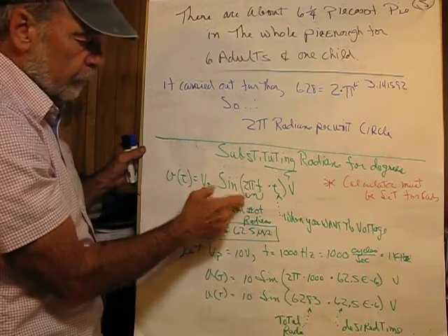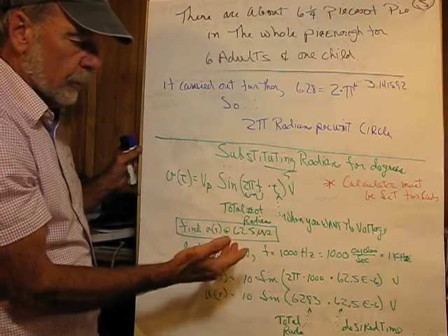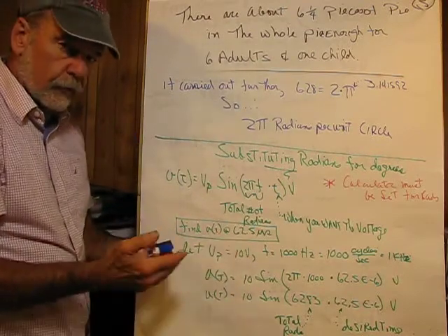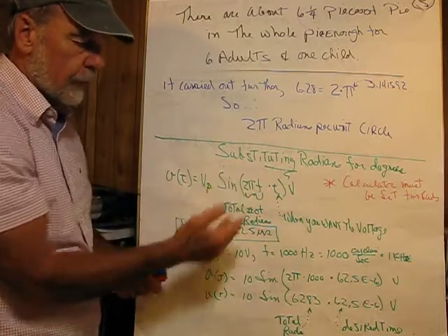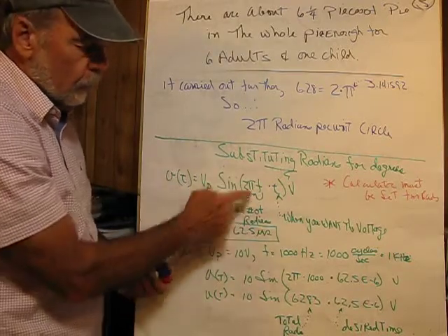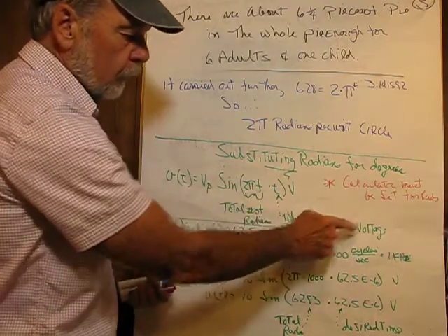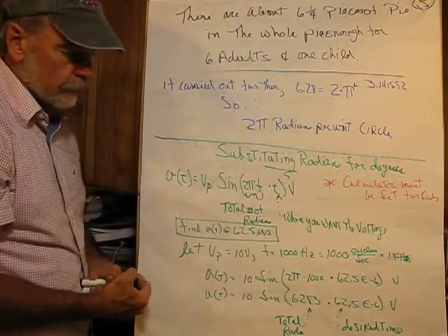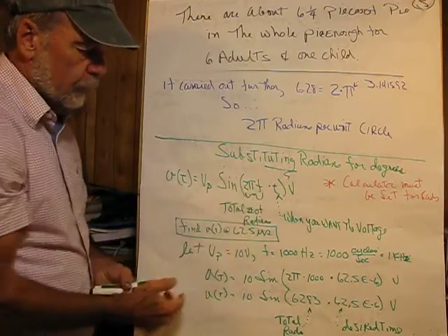So down here we'll see a little bit later that for a 1,000 hertz, cycles per second, sine wave that would be 6,280 something. Then we're going to multiply it by t in seconds, and this is when you want the voltage. Okay, so total number of radians that we're interested in times t.